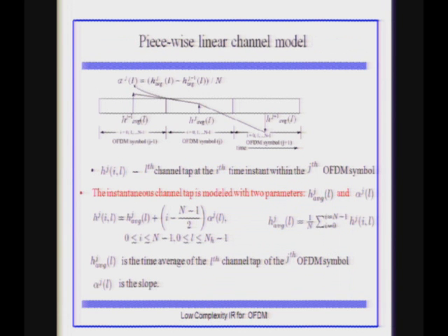Okay. So we use a very simple model. We use a piecewise linear model. It's not our idea. It was published before. What they do is, at normalized Doppler values up to 20%, which is where L is 1, a piecewise model for the channel. Remember, the channel is varying. Now you're trying to fit a model for that and find the parameters for that. And using those parameters, you try to find the channel instantaneous, the channel tap values for each of those.